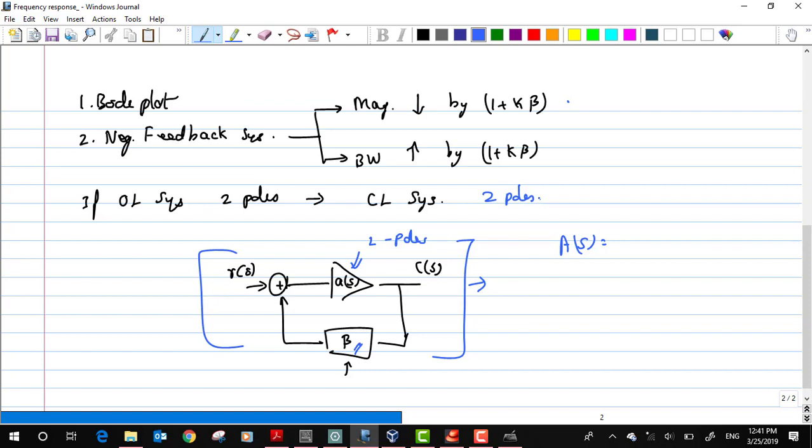Okay, only for a closed loop system do I want to apply the stability analysis to study the stability of the system. Now, we know that there are two types of closed loop systems. One is positive feedback, the other one is negative feedback. Out of these two, which one do we generally go for stability analysis? Negative. Okay, so it is only for the negative feedback system we go for stability analysis, not for the positive feedback, because we know that it oscillates, so there is nothing to control. It is only for the negative feedback system that we will go for the stability analysis.